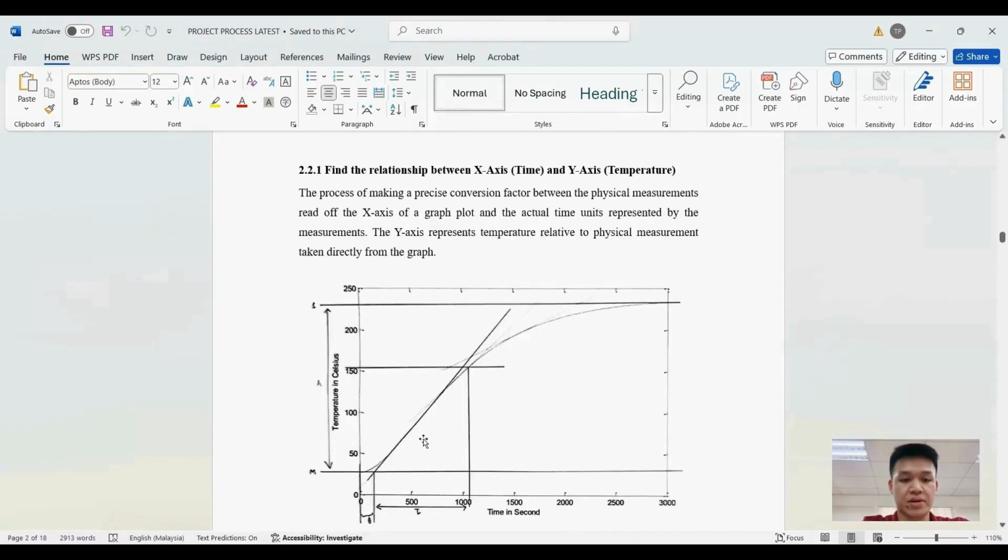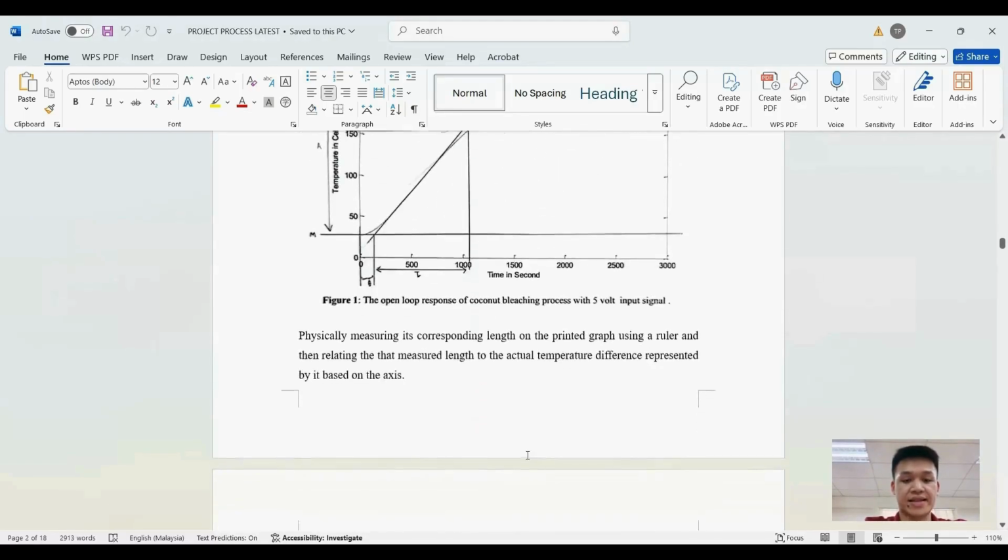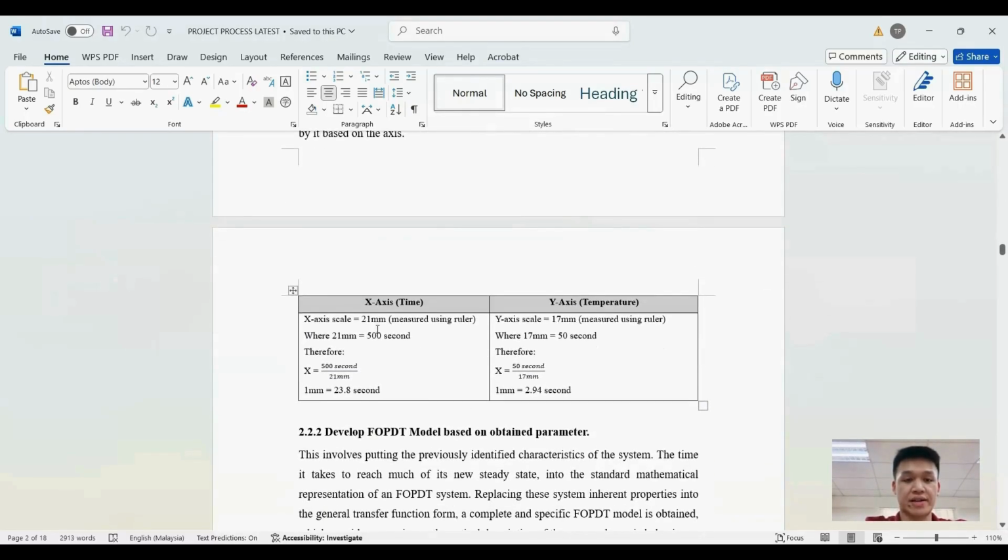Draw the inflection point line, and next draw the horizontal line for the minimum value. Draw the vertical line at zero time, and draw the vertical line at the intersection of line step 1 and line step 2. The delta is the time between this line and this line. Find the relationship between the time and the x-axis sketch, and find the delta in seconds.